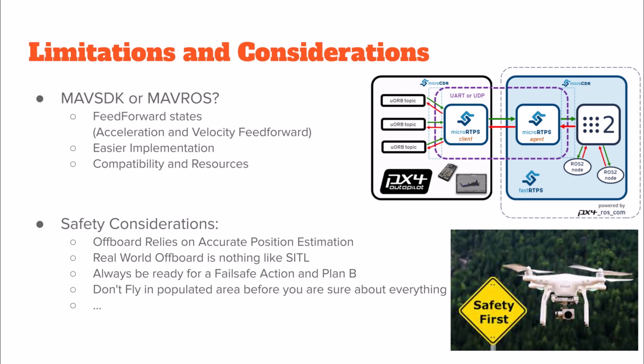MAVSDK, by the time I'm recording this video, has a very important limitation, which is that it cannot feed forward the acceleration while feed forwarding the velocity and the position setpoint. So you have to only use velocity feed forward while sending your position setpoints. For basic maneuvers, it's okay, it works just fine.